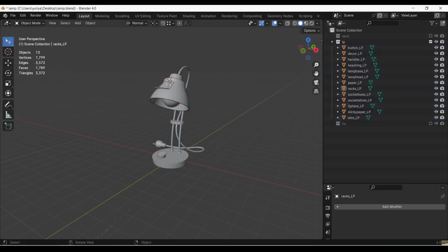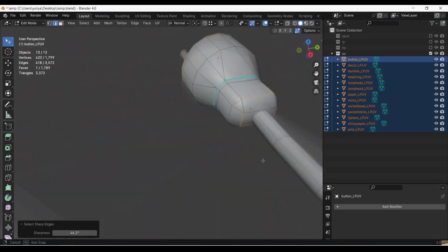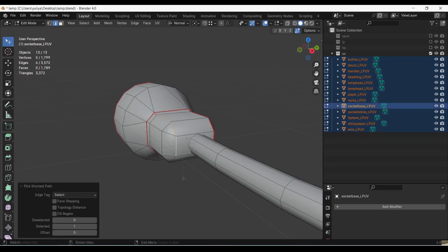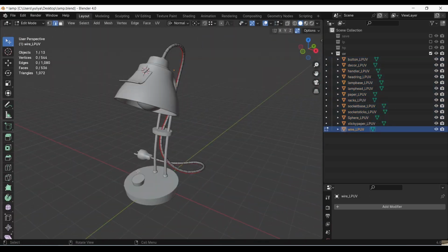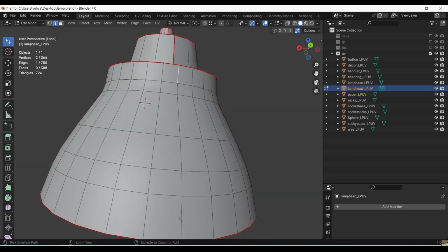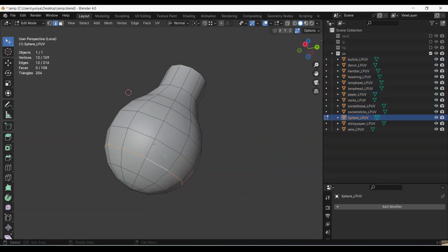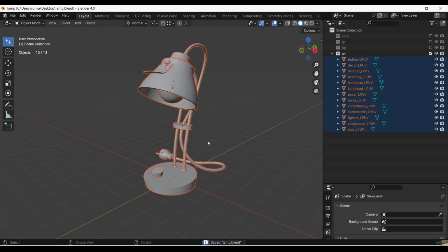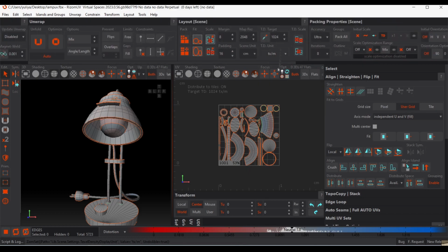The next step, after the low poly model is ready, is the creation of the UV map. I make my work easier by automatically selecting all the sharp edges by adjusting the angle and marking them as sharp and as seams. It's very important that there is a sharp edge where the seam is on the model, otherwise there will be unpleasant creases in the texture. The cylinders need to be cut along the top covers and along one of the edges.